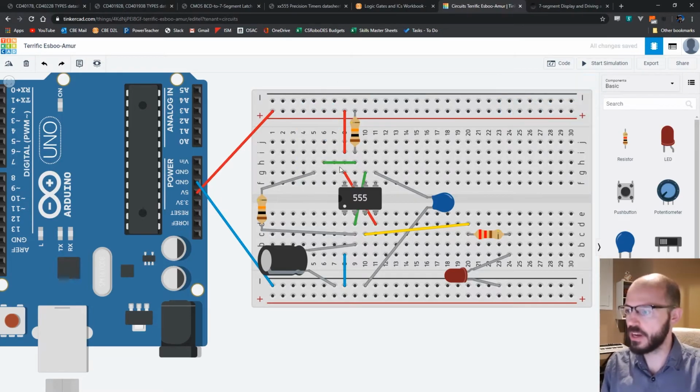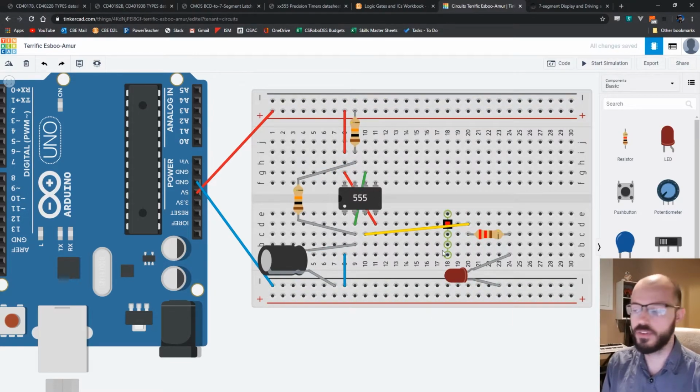I'll just set this back to the way I originally had it here. And we can actually get rid of this just to make things more clear. The absolute bare minimum that you need to get a flashing light on a 555 is this circuit. So just our 2 resistors and our capacitor. We've got 3, 4 jumpers, and then whatever else you need for your output. So very simple, very straightforward.